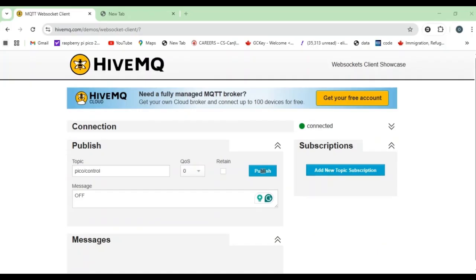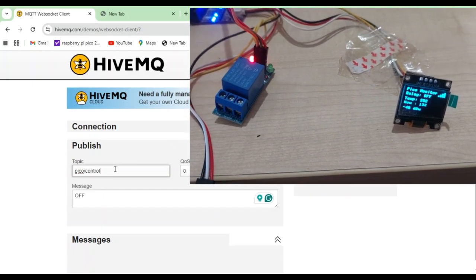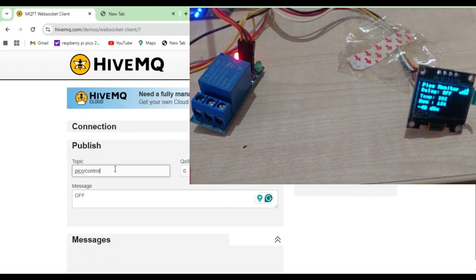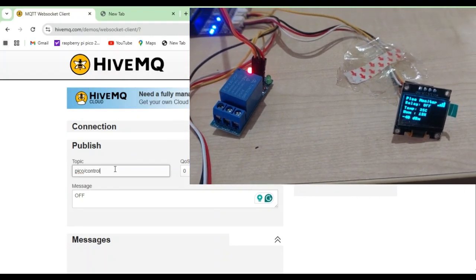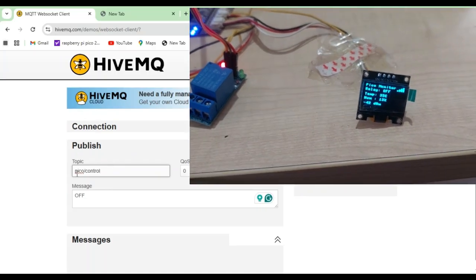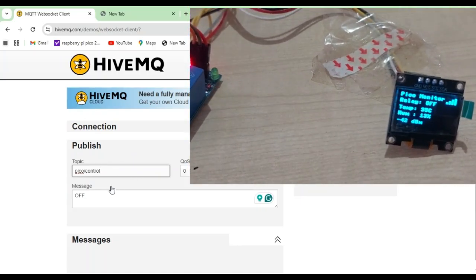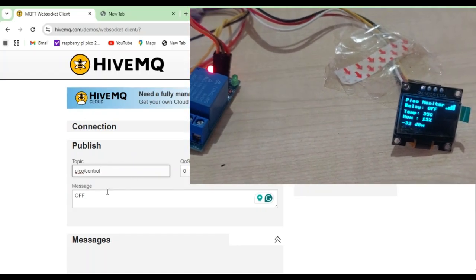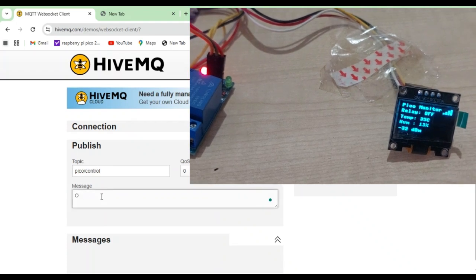Now that our system is up and running, we're going to use an MQTT client from this link. I'm going to share the link in the description of the video. First we need to set up the topic which we want to use to publish to our Pico-W. Remember, our Pico-W is subscribed to this particular topic.